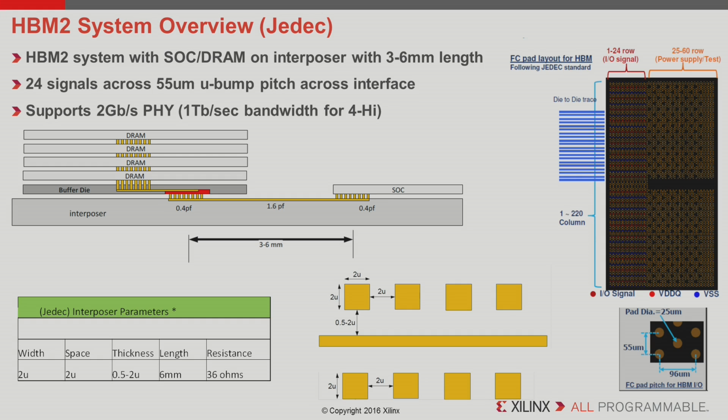So JEDEC came out with some guidelines. To run at these speeds and a UI of 0.8 or higher, you could conceivably have a 3-layer scheme with the 4 micron pitch, a ground shield layer, and up to a max wire length of 6 millimeter.